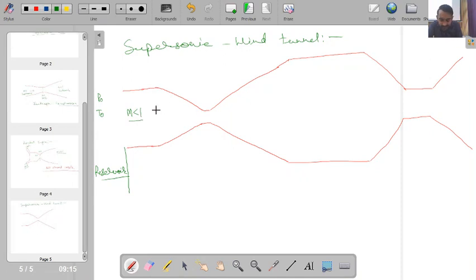This Mach number less than 1 enters into the convergent section. In this convergent section, its velocity will keep on increasing, and we will design this convergent section so that at this minimum area point I have Mach number equal to 1. After that I will have the divergent section where my Mach number will become greater than 1. So here I will have a supersonic flow situation. This section from this point to this point is a nozzle.